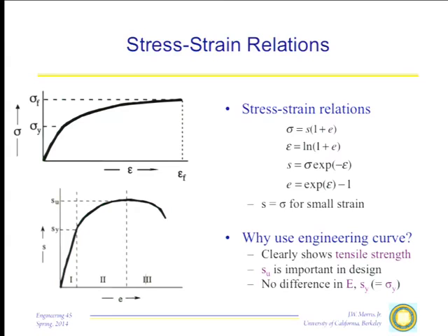If you're talking about fundamentally what's happening in the material, you don't want this, because beyond the elastic region, it's not really telling you what's going on fundamentally. If you want to know what fundamentally is happening in the material, you have to flip over here to the true stress, true strain curve. And this is the way to do it. So we have two ways we measure stress and strain. One representation is useful for design engineering purposes and is almost universally used for that purpose. It governs the handbooks. The other is useful for more fundamental investigations, since it gives us insight into what's really happening in the material, and that's the true stress, true strain curve.